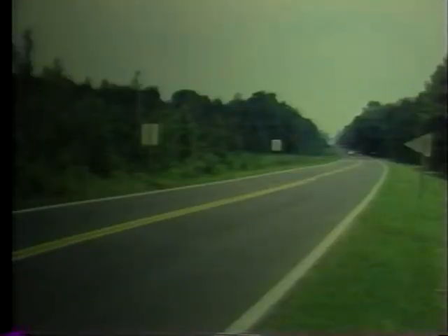Here, you can see an example of lack of attention to a clear area. The ditch was lined to reduce erosion and associated maintenance, but then the luminaire support was located right in the ditch lane. Here, the complete median was lined and a traversable grate was installed, but the traversability is ruined by the fixed base support. Trees in the clear zone are also a serious hazard to vehicles that leave the road.